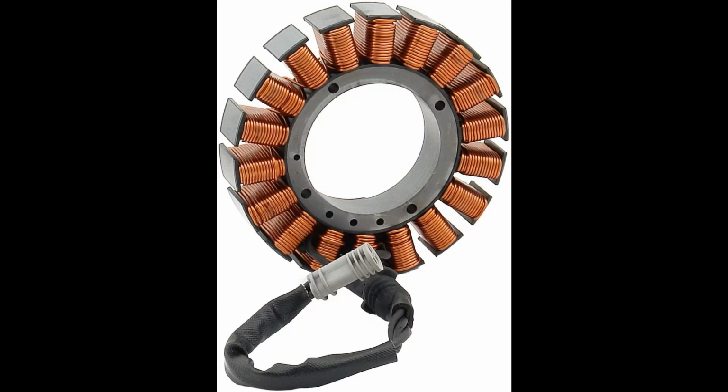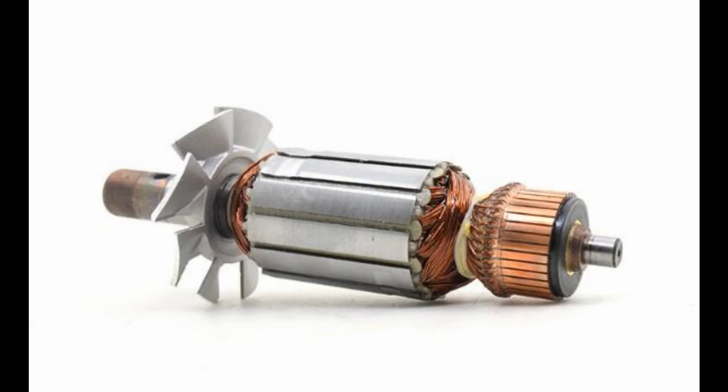Electric motors and generators work essentially the same way. Every generator and electric motor has a stator and a rotor. The stator is the stationary part of the motor and is made up of many copper coils. The rotor is a part of the motor that rotates. The rotor is made up of several magnets, and when the rotor spins, the magnets pull electrons through the copper coils, generating an electric current. For a motor, the coils in the stator would receive power, which would spin the magnets in the rotor.